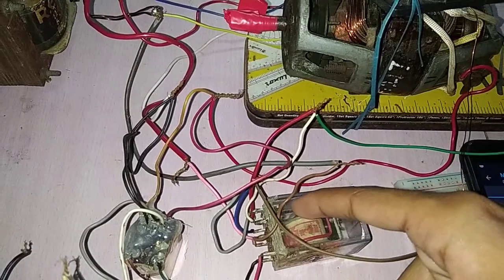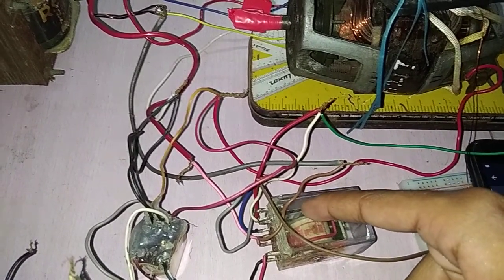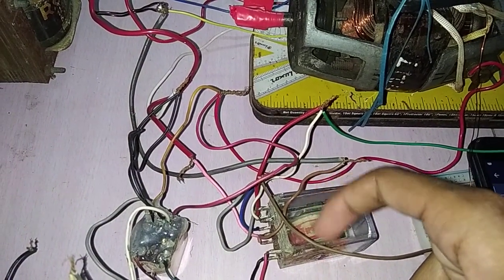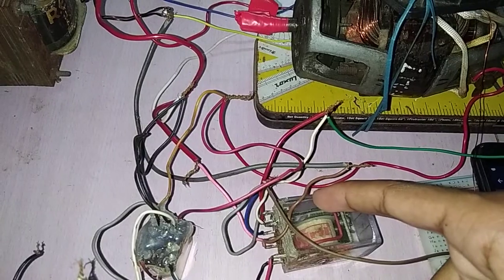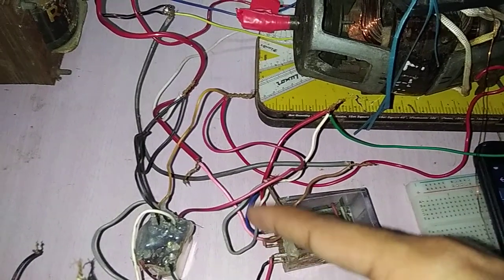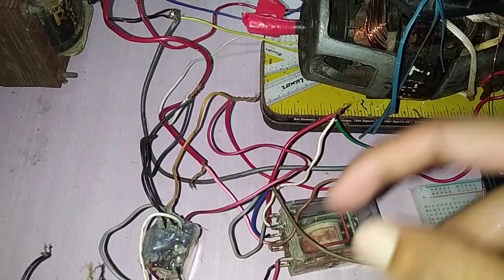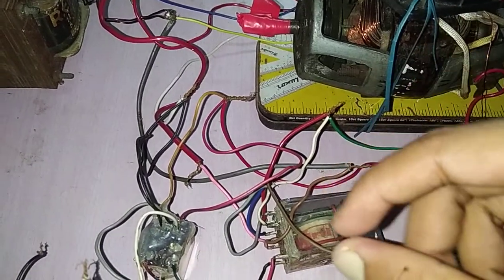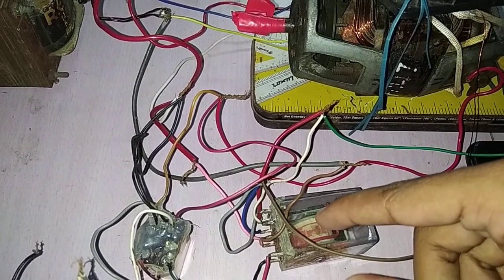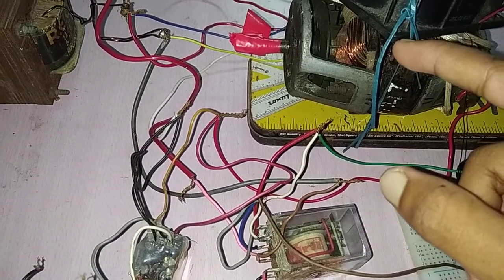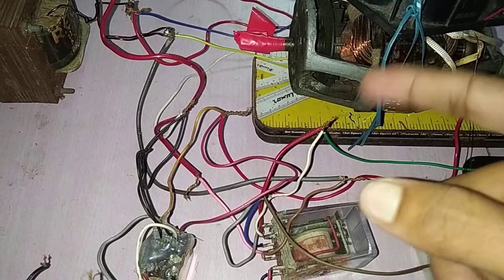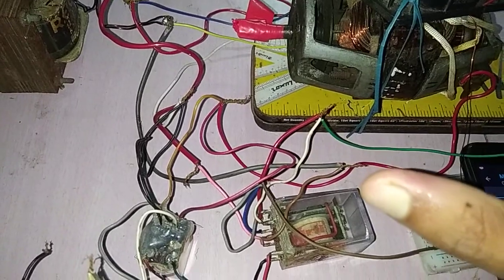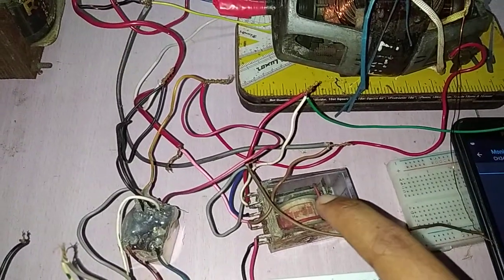What is happening here? The contacts at first were NO, now have become NC. This tick tock happens, and these contacts I have used to connect the field winding to change the polarity. So when the relay is off, the motor is rotating in, say, clockwise direction. When the relay is on, the motor is rotating in anti-clockwise direction. Simple funda.